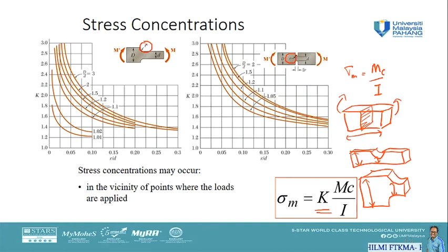The larger the value of r, the smaller the value of k will be. Once k is smaller, the maximum stress due to the stress concentration will also be smaller, and therefore it helps in designing or using cheaper material for any kind of application.